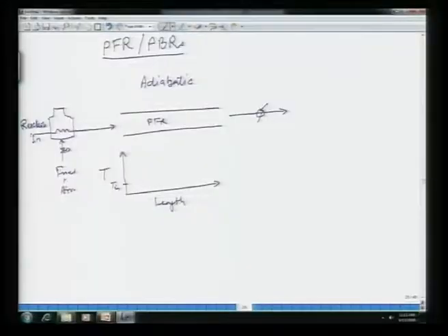All right. So, as this plug moves ahead, it has gained the reaction heat. The reaction heat is converted to sensible heat effect. So, the temperature rises because the plug is retaining the heat released by the reaction, therefore, its temperature keeps on going up. Now, as you keep moving down the reactor, initially your mixture was reactant rich. As I have moved down the reactor, now my mixture has got lots of products, little bit of reactants.